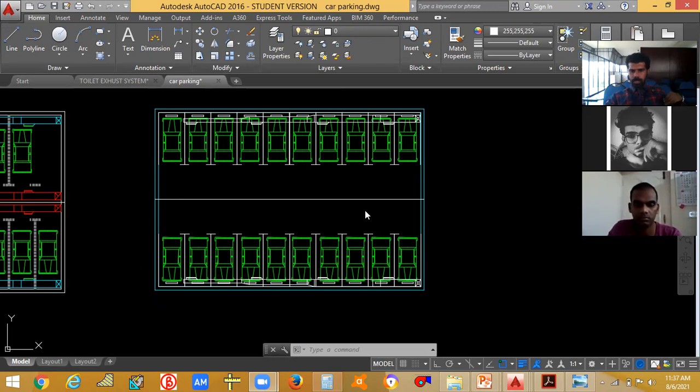Shepherd is saying that first we have to classify the air quality, then calculate the CFM. Kirti is saying that decide how many ducts are required. But before deciding how many ducts, we need to decide whether it is ducted or non-ducted. Vinu is saying that again, we have to decide ducted or non-ducted.